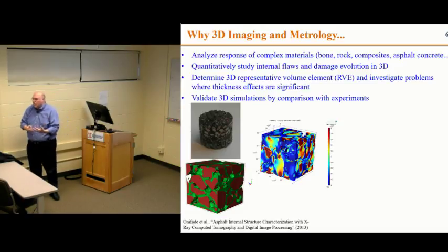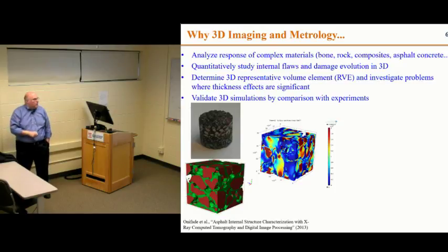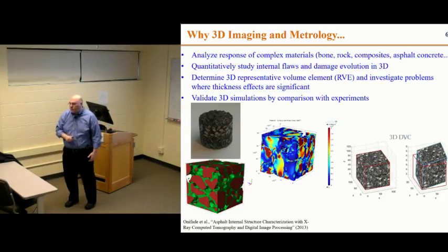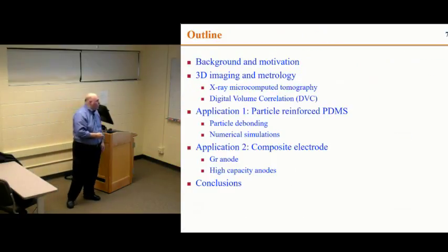So we would like to be able to do a lot of these things that are typically looked at only numerically, also with experimental methods. Study damage, do things like quantifying representative volume elements and stuff like that. When you do upscaling of numerical techniques, this is an important concept. The RVE concept is very important. So far, again, it's something that's only been determined experimentally. And like I said, we also want to be able to, at the end of the day, validate simulations, complex 3D simulations, not solely by measuring what happens on one surface, but being able to see what happens inside, right? So we would like to be able to measure the 3-dimensional deformation of something, not merely the surface deformation, and we're going to do that with what we term digital volume correlation, or what I denote here as DVC, and that's what I'm going to talk about today.